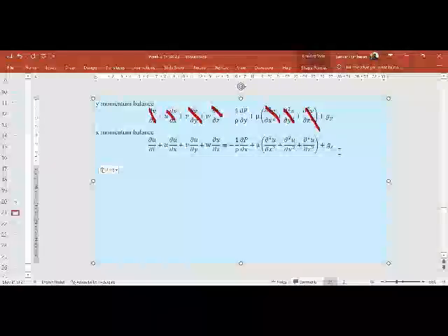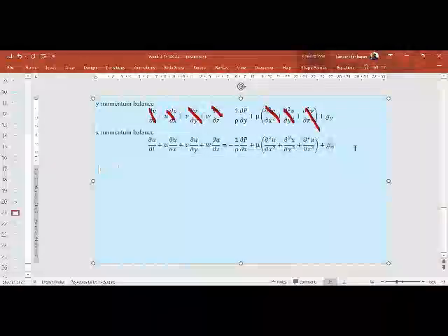And yeah, so this is again gx, not gz. So let us take now what all needs to be cancelled. We'll just take away the unsteady term. We know that u is not a function of x, v is equal to 0, w is equal to 0, so these three terms will go away. The pressure gradient will remain as it is.